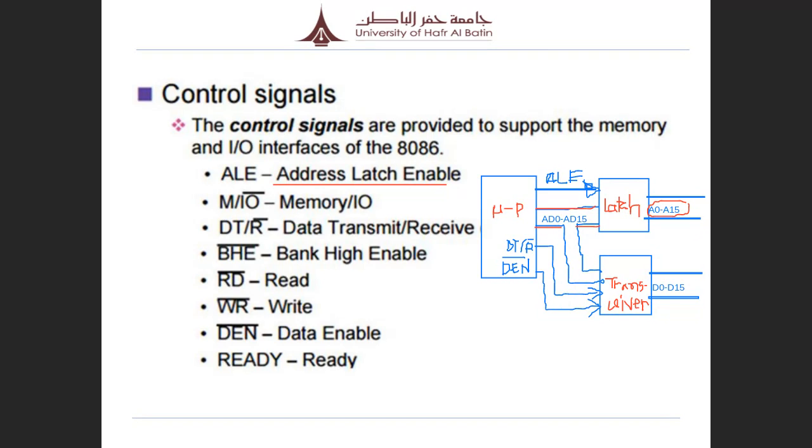After a short time, the ALE signal becomes inactive, or low. During the active time it is high. Then the latches are active, and then the ALE signal becomes 0, so the latches are inactive and no more address information can go out. Once the address information is done, the microprocessor uses the pins for data. Because the latches are inactive, data cannot go and mix with the address information. So data is now for here. You can see this is for data.